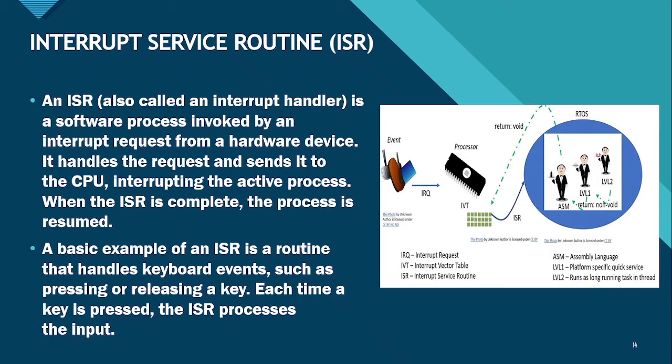Now, the interrupt request is accessed and it goes to the interrupt service routine through the interrupt vector table, and it acquires the address of the interrupt service routine and jumps to the interrupt service subroutine to access the request and execute it. After the execution of the interrupt request, it comes back to the stack and pops the program counter address to find the next instruction and execute it. This is how an interrupt is executed.